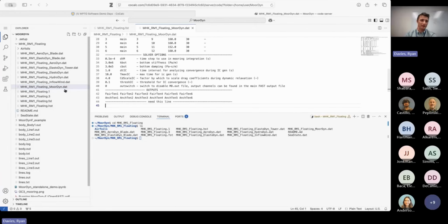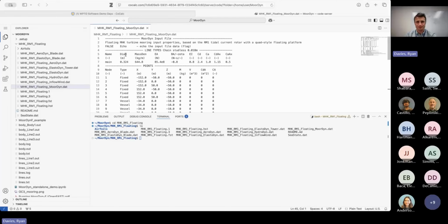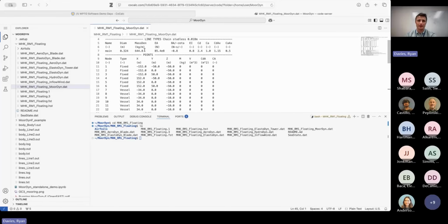Next, we're going to open the MoorDyn input file, and look at the system that we have set up. You can see we have one line type. Someone defined it up here and said it was chain, but all that's important is that you have your properties here. We define the stiffness and our damping. Someone's given this a bending stiffness, and then we give it some hydrodynamic properties as well. I'm saying someone because these are the exact input files from the regression tests in OpenFast, so I didn't set these up, but these are what we commonly point people to.